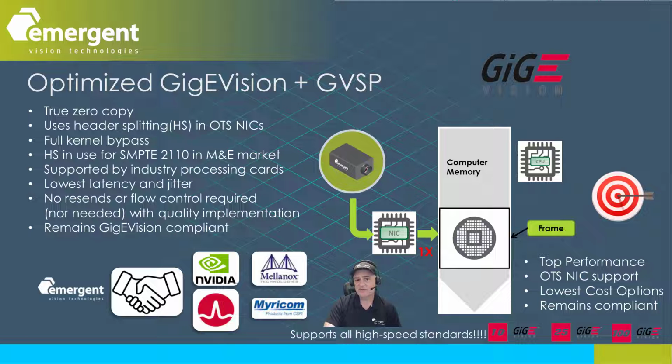Much of this can be attributed to zero copy technology and adequate buffering on the frame grabbers required for CXP. Low-cost NICs often lack sufficient buffering capability. However, modern NICs are readily available at cost-effective price points with ample physical buffering.